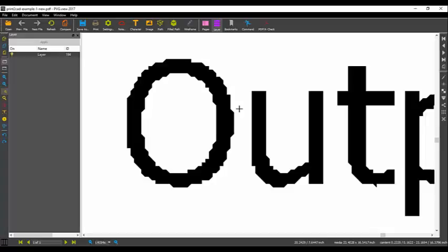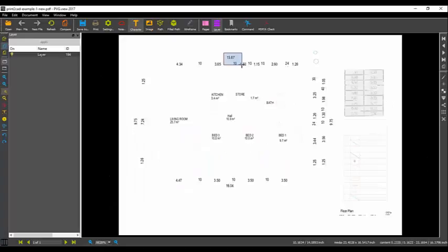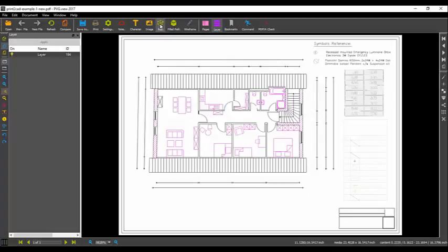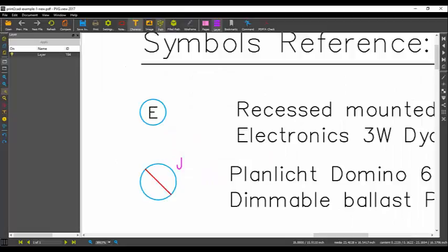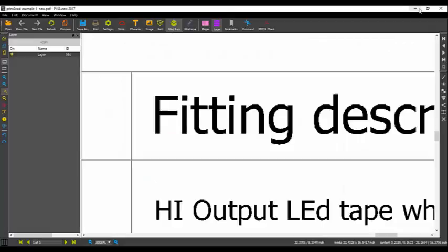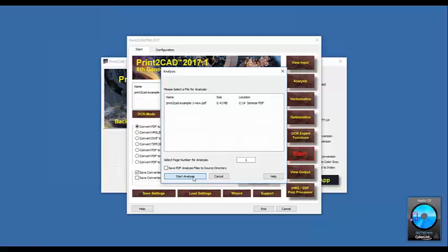This is again a plot into PDF in 300 dpi made by AutoCAD. And what you see here, this is not a text. This is only a hatch of a text. This is not a native text. If you separate, for example, here you see this is a text. This is a native text. But this is something different. This is an image, and this is here a path, like text in the form of path, and this is here filled paths. Okay?